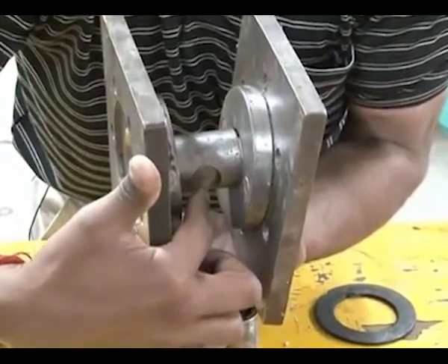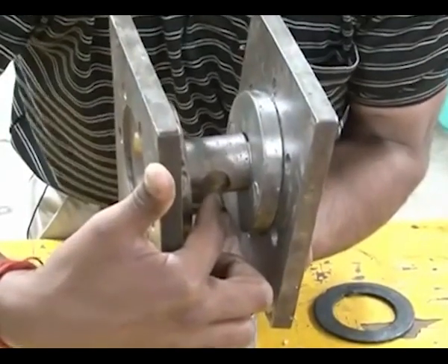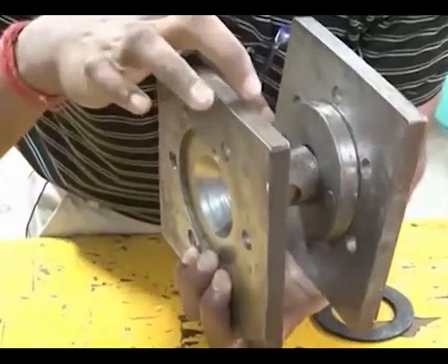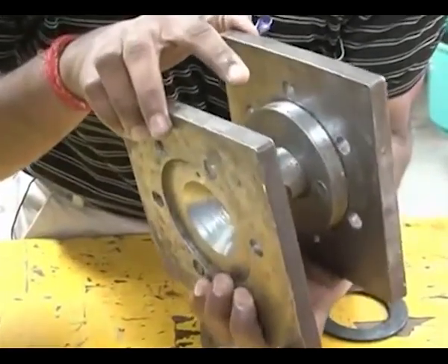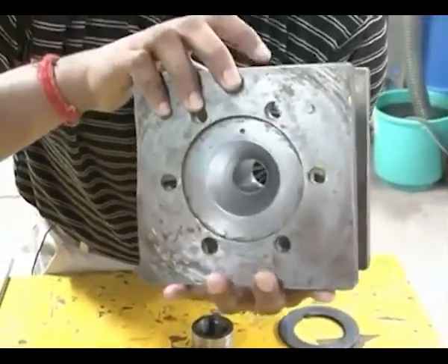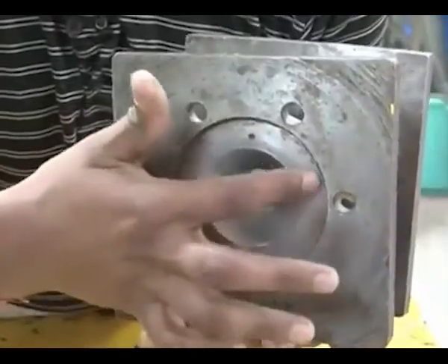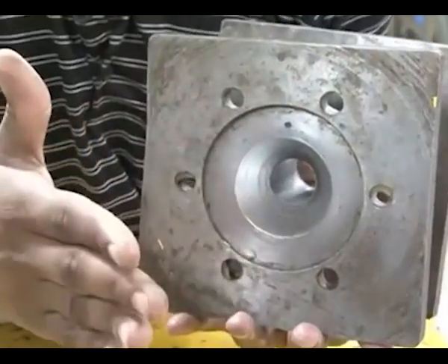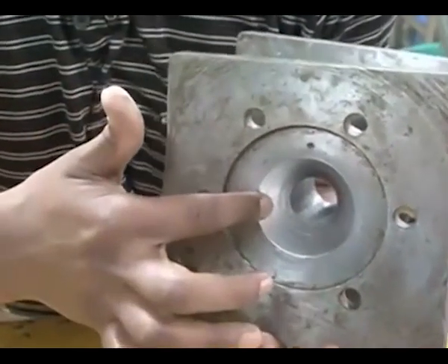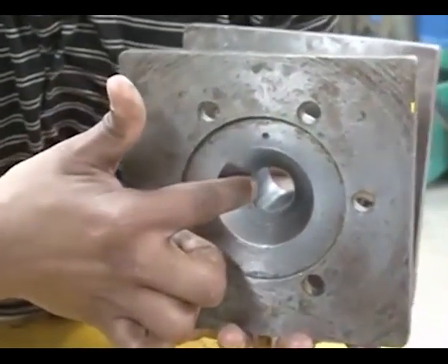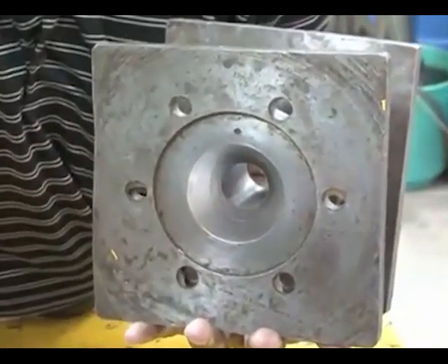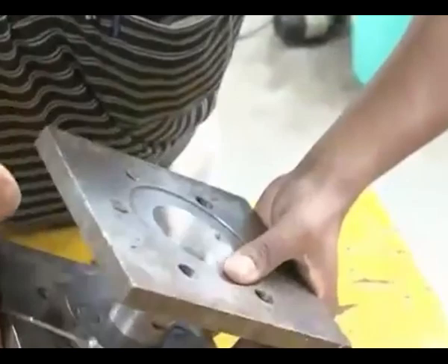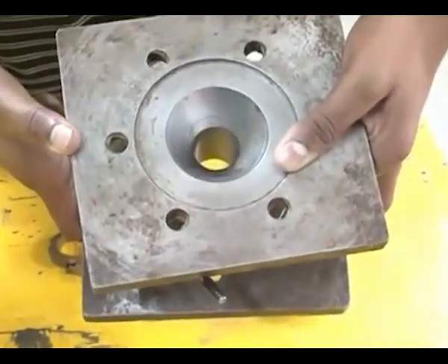This is the place where we place the acoustic emission sensor for measuring the acoustic signal while the finishing process is going on to control online surface finish measurement. And you can see this tapered portion. This hole size is equivalent to the bottom medium cylinder hole, and when this medium comes here, it gradually flows through a tapered portion and enters into the workpiece region and comes out from again a tapered portion.